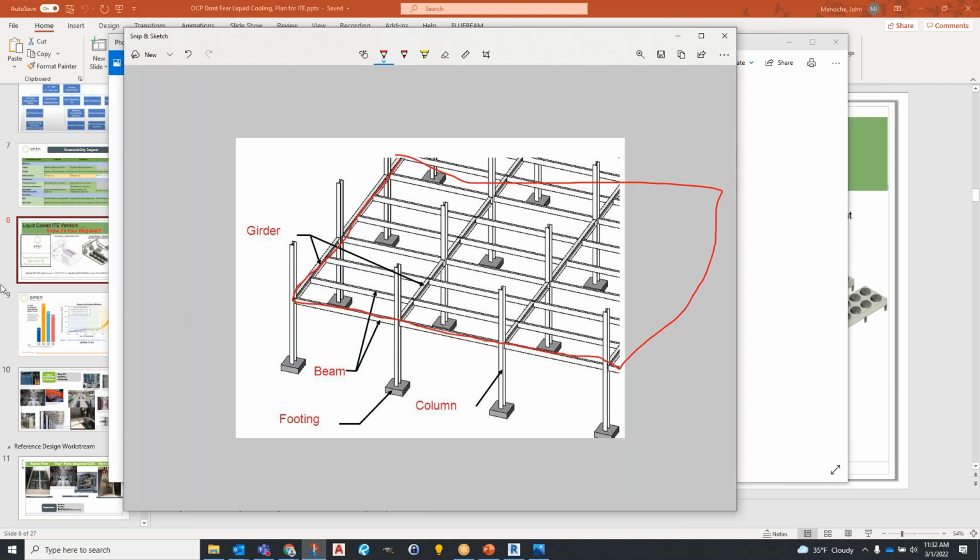But if you provide something else, for example, between these four columns, the overall average floor loading is going to be not exceeding, say, 250, the level of information you provided is a little bit less, because then they still have to worry about the point load nature of things on the in-between girders or beams and the actual thickness of the slab, etc. When you say structural design satisfying this floor loading, that is a complete set of requirements for the entire structure assembly.